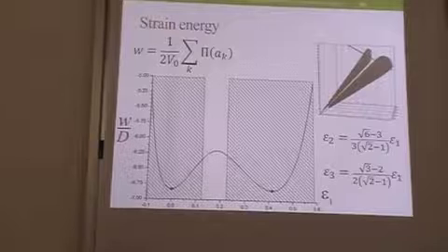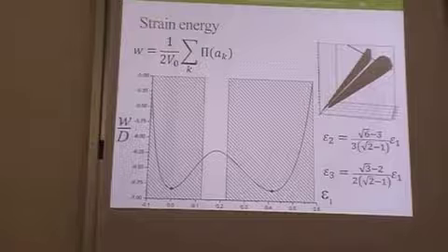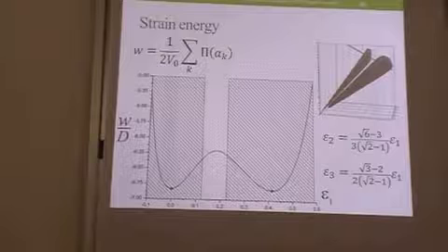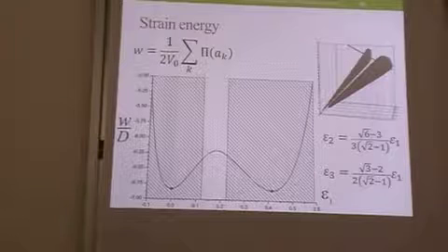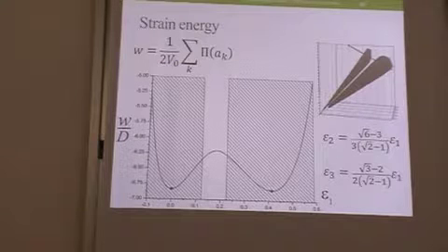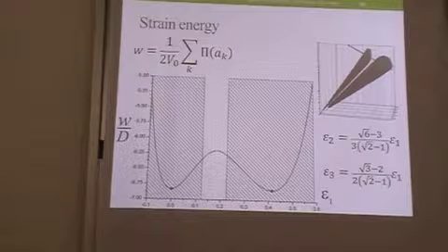And there is this strain energy profile on this line, and we see two minima. They are the same depth because the two lattices are close packed. They have the same coordination numbers. It means that they should have the same strain energy, and the influence of the farther neighbors, which differs a little bit starting from the third sphere, is negligible. That's what we see.